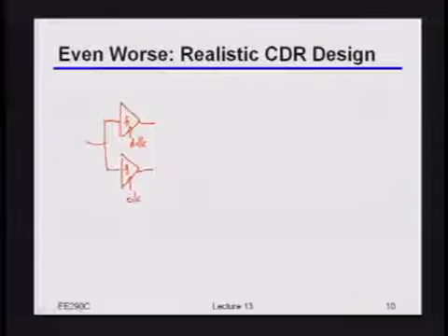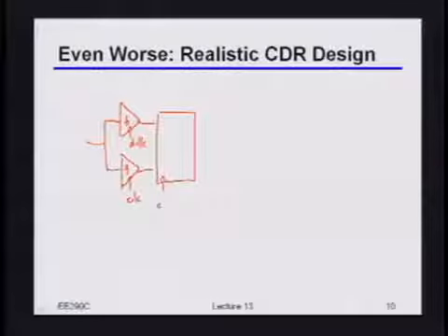Then what I will basically do is shove this into something that looks like a big bank of flip-flops, where there's basically going to be two clocks in here. One is equivalently the data clock, meaning as an example, 12 gigahertz if you're doing a 12 gigabit per second link. And then the other one would be something like the data clock, just as an example, divided by 10. Or maybe divided by 12, or even maybe divided by 24, or something like that.